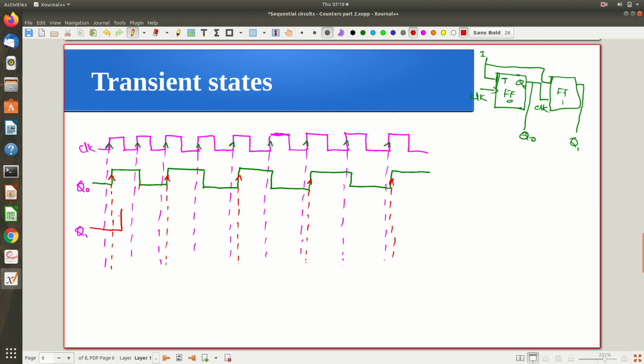So flip-flop 1 will have some delay to process the input to the output, and that is what is highlighted here. So after this much time, why this gap? So that is for that processing purpose, right? Similarly, it will continue. Again, now it is supposed to trigger, but it will extend like this. Okay, again it will toggle, it will continue, then it will toggle after that delay. Again it will continue. So this is actually your rippling effect, right? So that delay that is getting accumulated from one to another like this is what we call a rippling effect. Okay, hope the idea is clear now.